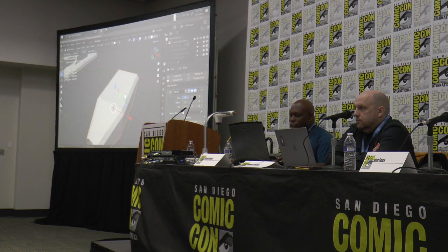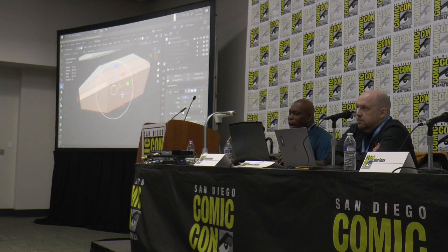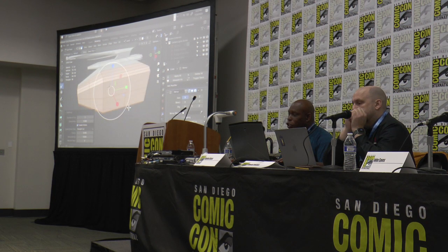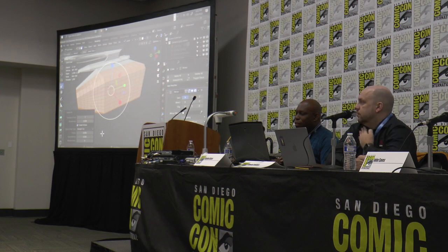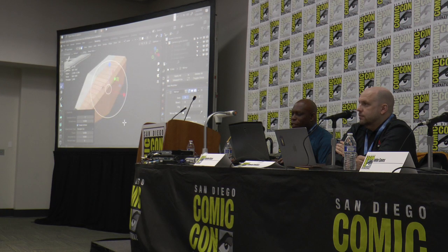Okay, so let's go inside, go back to edit. I'm going to select all. I'm hitting the 3 key for face selection mode. A key means select everything in there, right? I want to subdivide. Right click, subdivide. It starts subdividing a little bit. You're going to see why I'm doing this in just a minute. Now right down here is my options for my subdivision. It's only one subdivision. Click to go to second, and then more, and more. Maybe we'll go one more like that, okay? All right, so a little bit much of it doesn't matter.